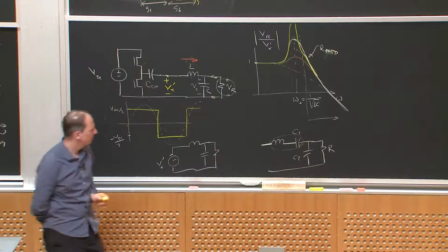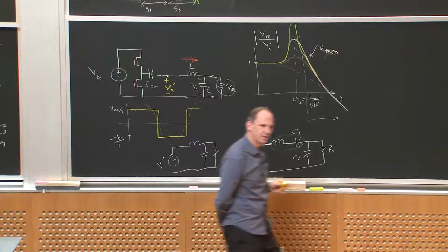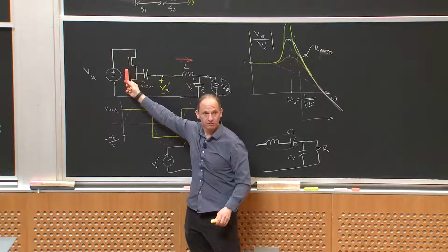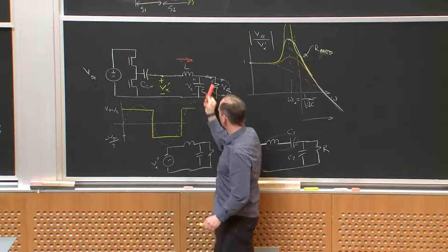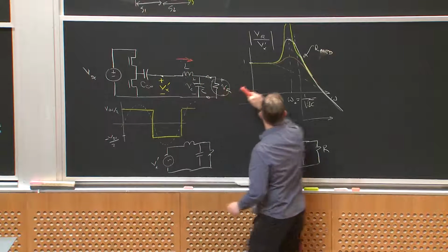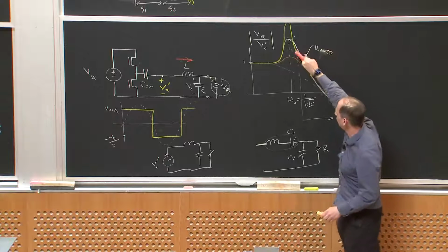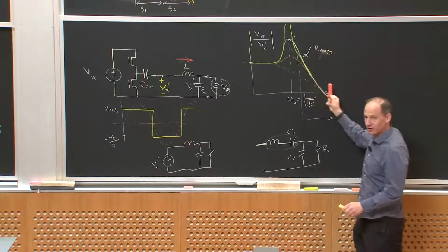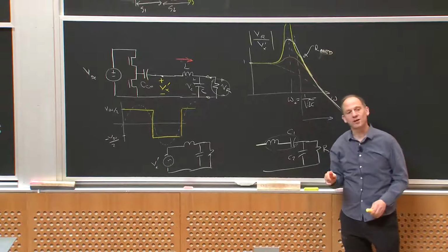All right? So how would I build a DC to DC converter? Well, maybe I'll use an inverter, create a square wave, use a high Q network to extract a sinusoid, and then I can use that to control voltage gain, right? Because I can control the amplitude of the current by varying frequency. And then I just run it into a rectifier.